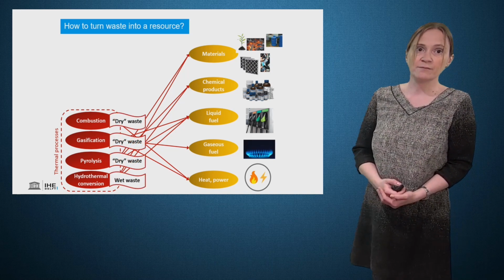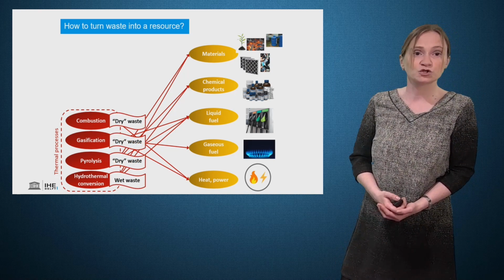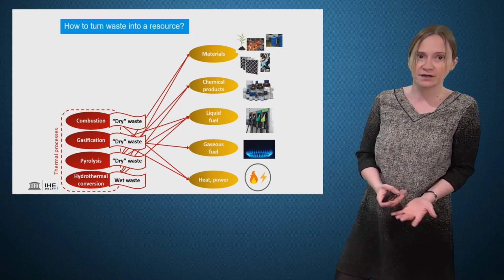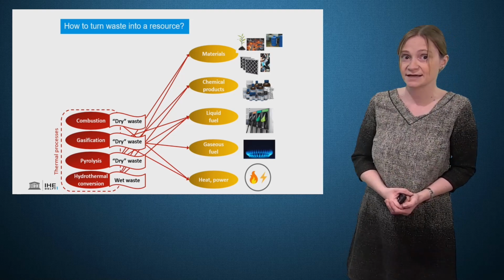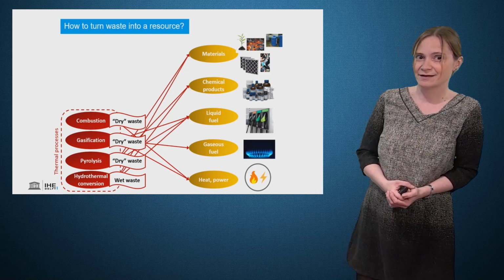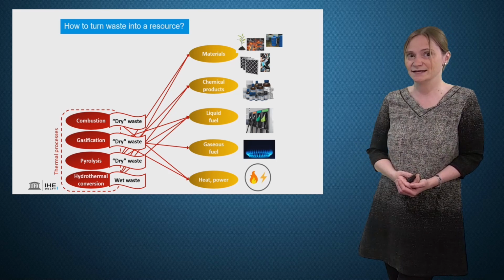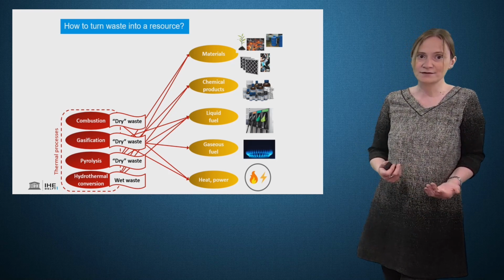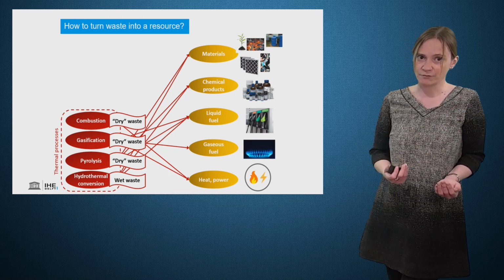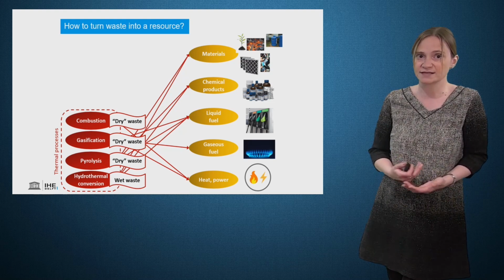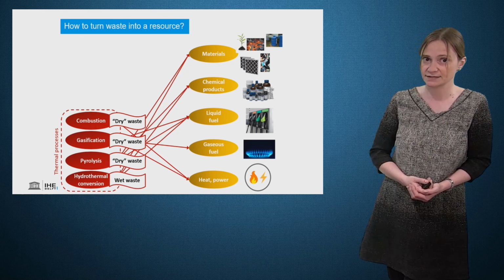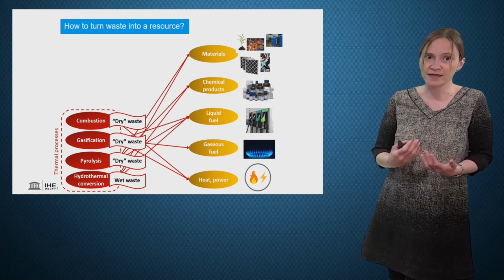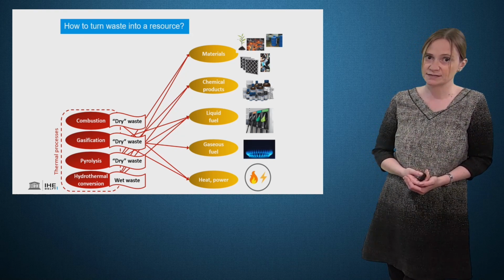Well, logically, thermal processes are more suitable for dry waste, and you may know why. Indeed, the basic principle of thermal processes is to heat the material, and therefore heat the water contained in it as well. Heating water is a very energy-intensive operation, and thus a very expensive operation that will decrease the viability of the overall process. It is therefore more viable to use dry waste in such processes.